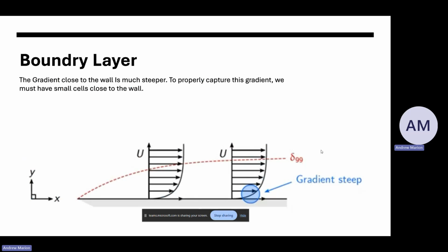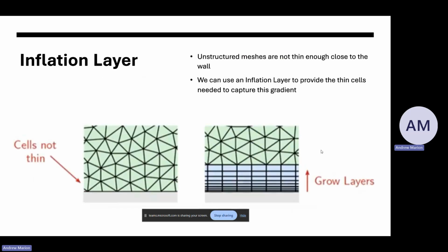So you need much smaller cells down here to capture that gradient, but as you get farther out, you can use larger and larger cells because it's not changing. It's the boundary layer that really makes wings do the things that wings do. So you want to resolve that properly, or your results can be off by a decent amount. If your cell height is bigger than your boundary layer height, it won't simulate it. So that's something you have to hand calculate a little bit and check yourself.